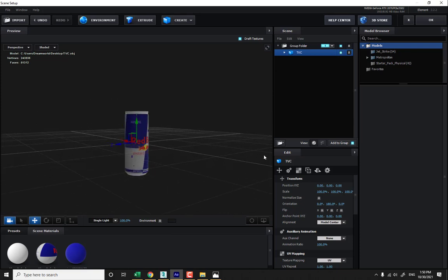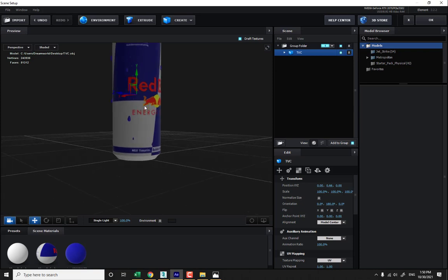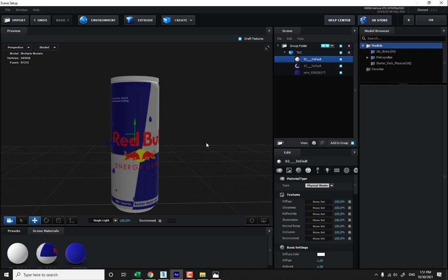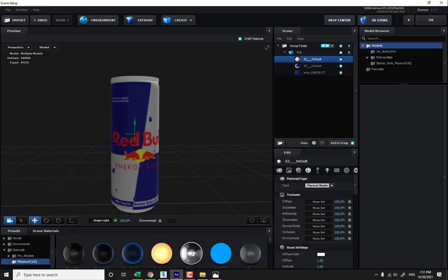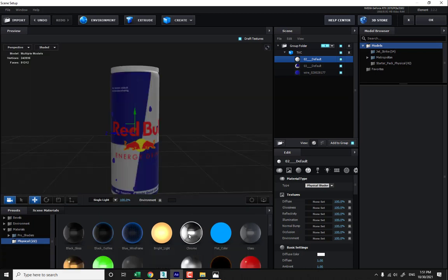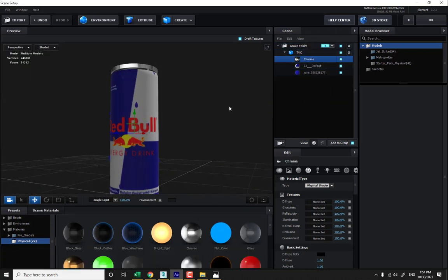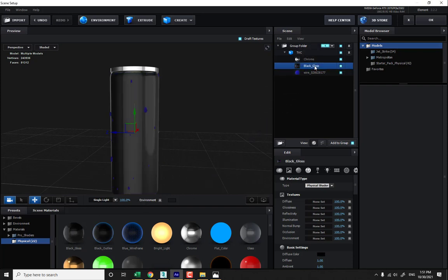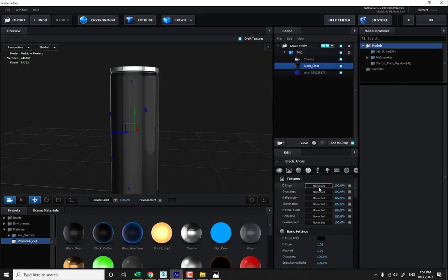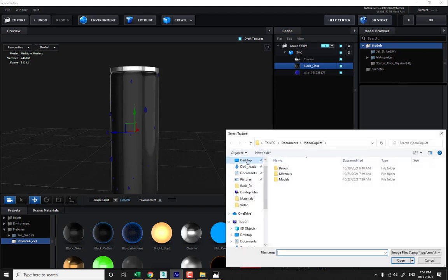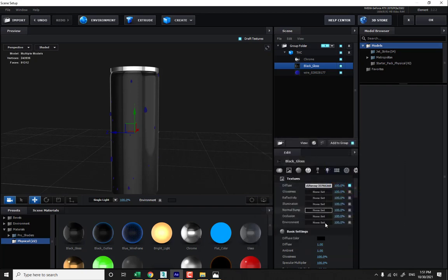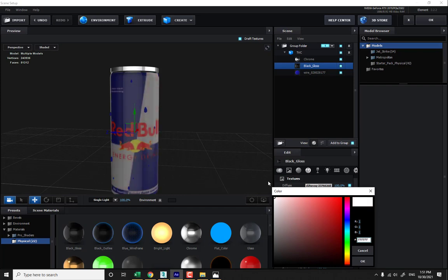There is After Effects. Yeah, so this is the red ball, and move it onto the gray. Okay, then open the materials. This material must be silver chrome, and this material must be... which one? This one. And select again and go back to texture, diffuse, and go to texture, desktop, select this one, press OK, and change the color to white.